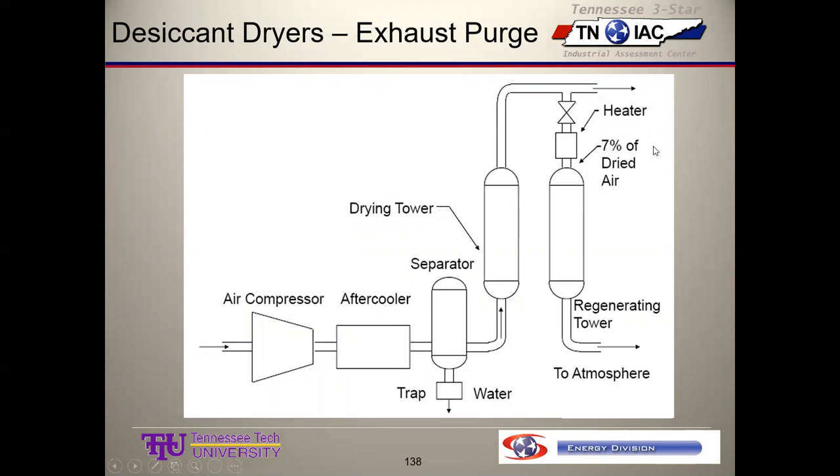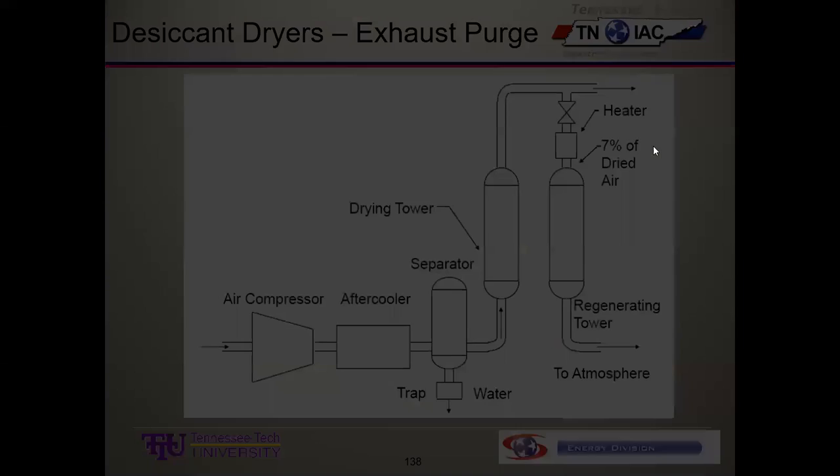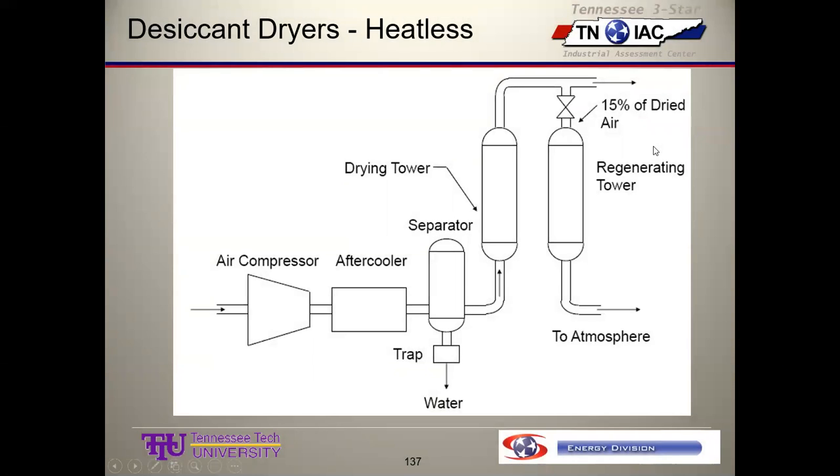So for example, you might have this 1000 CFM dryer and be running it with a 100 horsepower compressor. Let's say you're putting 500 CFM through this thing out of the compressor. Maybe you've got two 100s that you can run both, but you're only running one. So you're putting 500 in. This guy over here is still going to vent 150 CFM. That's the percent of the rating on the dryer.